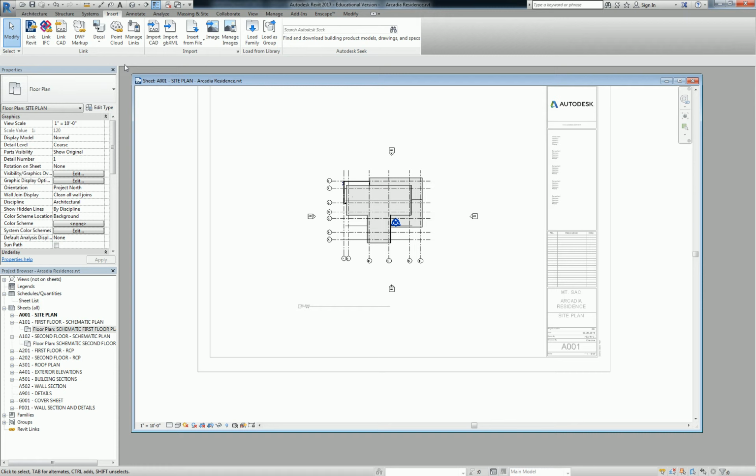They're tremendously different. If you import a CAD file, it's going to drop the CAD file in as if it's like a block in AutoCAD, and you can explode it and modify it and all that other stuff. But remember what I was telling you about line weight control? You never want to explode a CAD file in your project. If you need to, open up another project, explode it there, change everything to line types that you like, then bring it into your project. Okay, but anyway, that's besides the point.